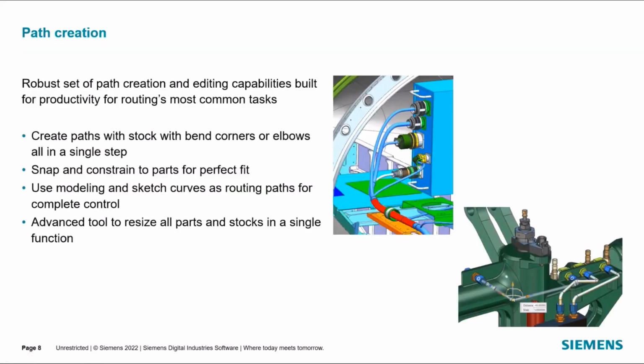So a lot of the work that we will do, and a big part of the demo, is routing the paths through an assembly. That's going to represent, of course, the area within the assembly where either your tubes or your wire is going to pass through and among all the different components in your assembly and connect to various components in your system. So we'll be able to use different kinds of paths. I'm going to use primarily spline type paths for wiring; for mechanical routing, it may be more appropriate to use linear paths. So I'll at least point that out to you when I get into the demo and show you where all these tools are.